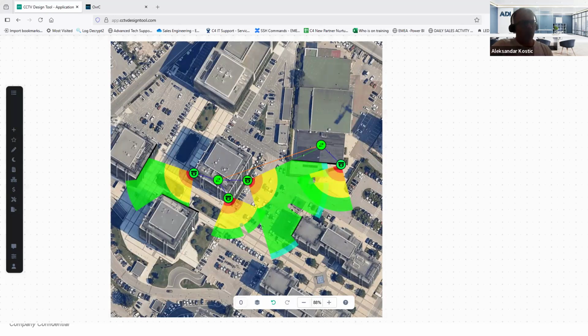Of course, we need to take care that each camera is less than 100 meters away from the switch, or more precisely, cable length shouldn't go above 100 meters, ideally not over 80 to 90 meters, which is the standard Ethernet limit, especially as we use PoE, so that cable should be a little bit shorter just to have a reliable connection.